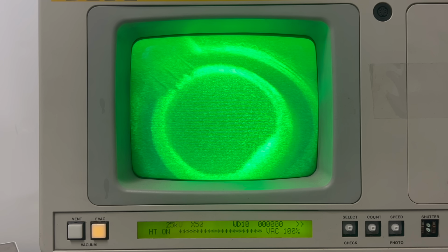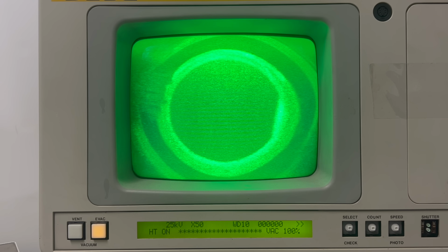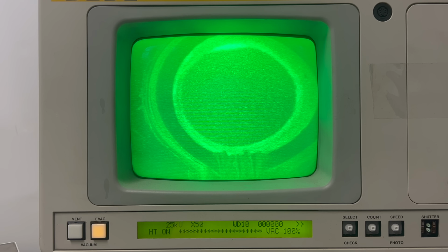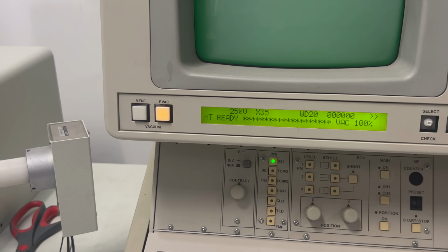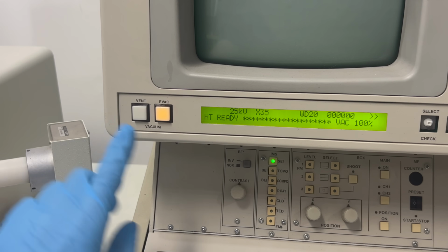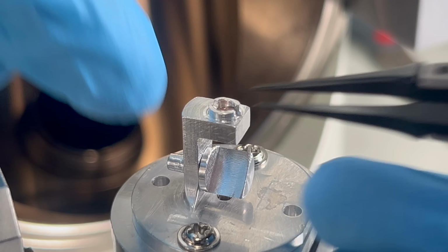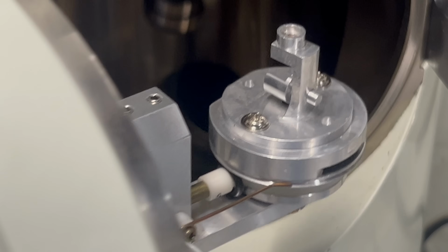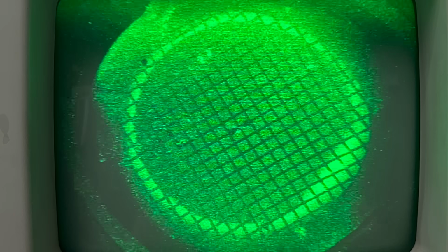Something that is important to note here is that the inside walls are glowing brightly. This is because the electron beam is striking the walls and causing them to emit a lot of secondary electrons. Installing the shield should fix that. Okay, time to add the TEM grid and shield. I vent the chamber to atmosphere and add a blank grid to the sample holder. Then I install the shield on top, and rotate the entire assembly so the mirror is pointed roughly at the detector. Alright, let's go. Nice, I can see the metal grid.